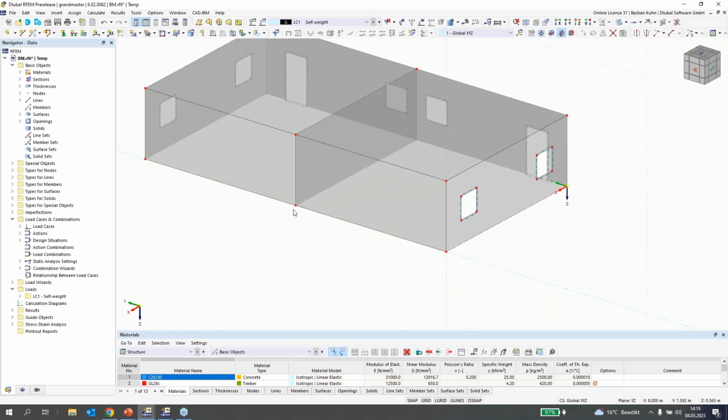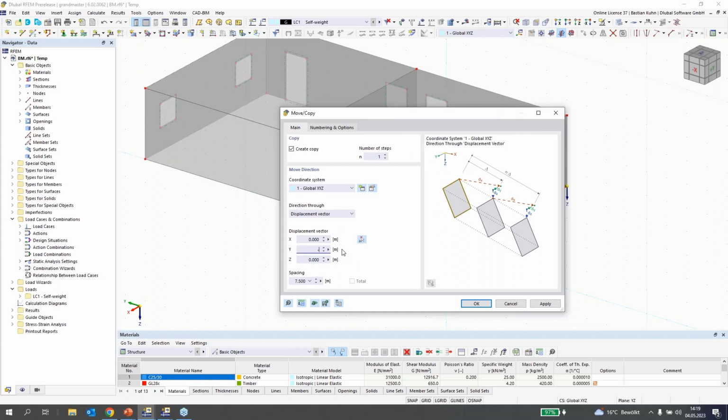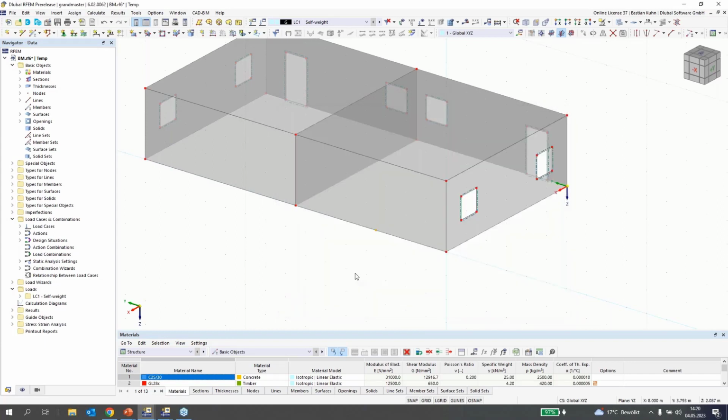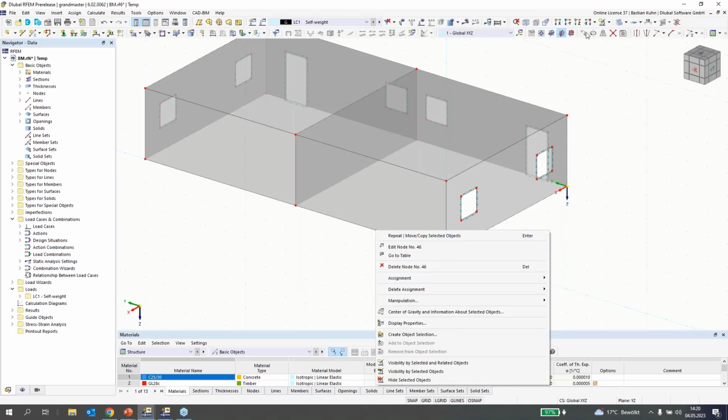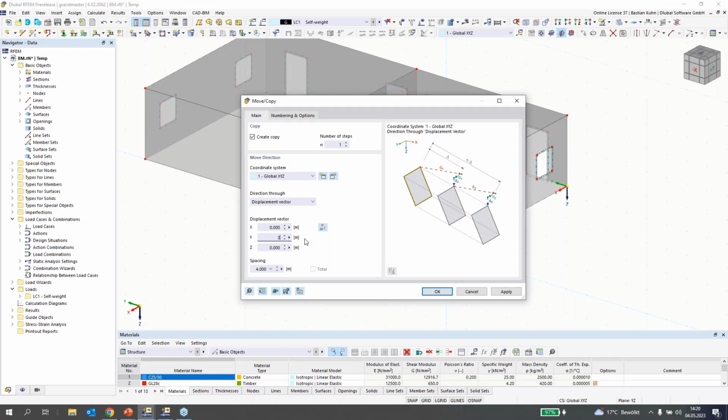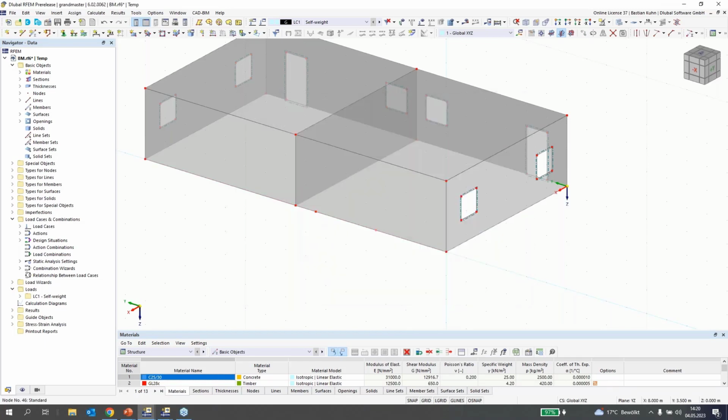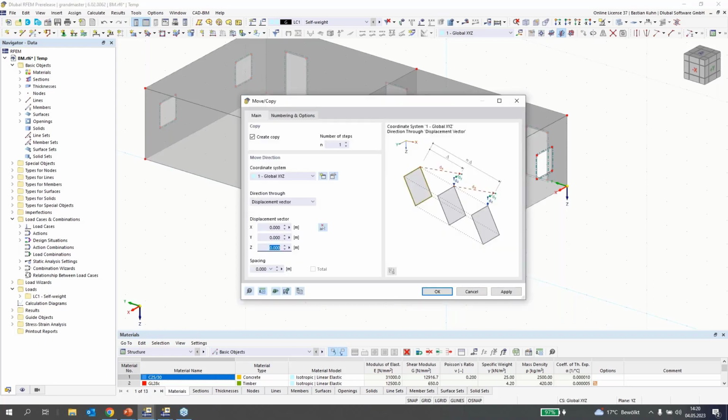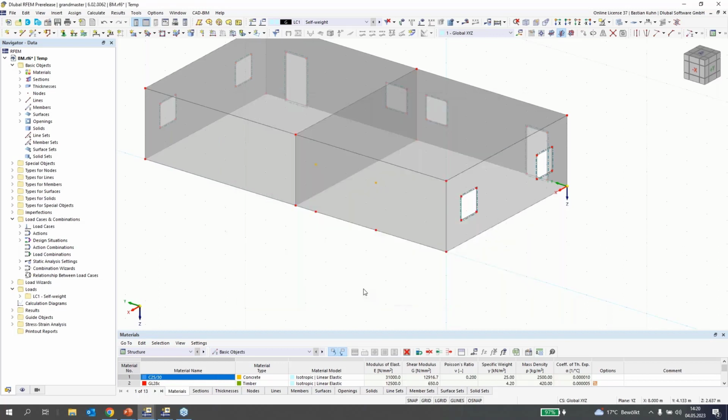Okay, no problem. We will copy that. Actually, so move copy in Y direction -4 meter, -4. And this one then 3 meters in Y direction plus. Yeah, now a little bit more effort, but I think it's good for you to see how to do that. Oh wait, we can actually move them or copy them upwards, 0 and -2 there, and then we can choose the opening with no problem. So there you go. And now we can select the opening, and now we can mirror it.